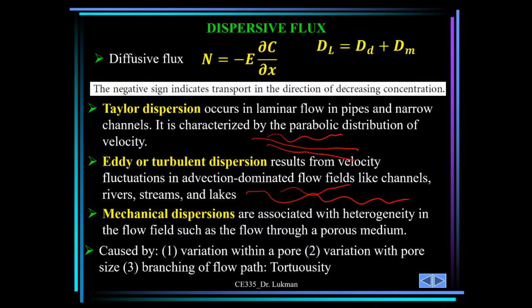And then this is called longitudinal dispersion, D subscript L, which is made up of molecular diffusion plus mechanical dispersion. D_L is sometimes called hydrodynamic dispersion. Hydrodynamic dispersion is made up of molecular diffusion and mechanical dispersion, and these two, when you combine them,